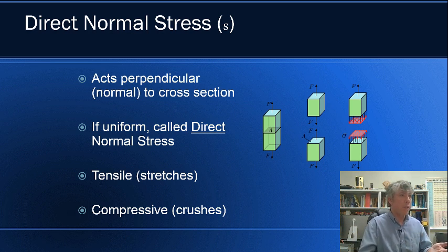So if you look at the picture here, we've got a body that we're going to imagine separating into two free bodies. From statics, you should realize that the force applied externally to this body would be the same force internally. It has to be for these two to be in equilibrium. But then that force would be, in reality, divided up over the entire cross-sectional area. All the cross-sectional area works together, kind of like those straws in a broom, to hold the material together and prevent it from failing and fracturing at this line.